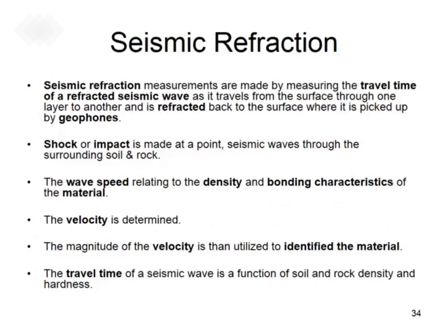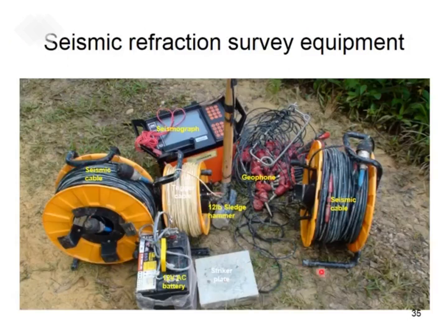For seismic refraction, the seismic wave refracts from one surface to another surface, and this refraction will be picked up by geophones. That's why in the previous slide, there must be some source and also some receiver. This is the equipment for seismic refraction.